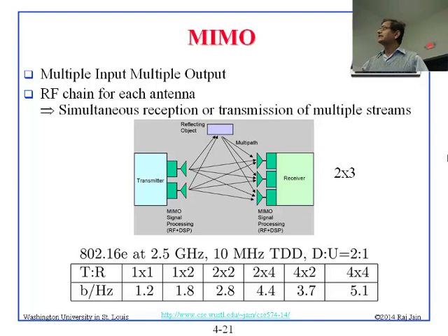That takes us to the next concept, which is MIMO, which you have heard before, I'm sure. But MIMO stands for multiple input, multiple output. Basically, if you go to buy anything today, it generally has more than one antenna like this. Right? In the old days, just 4 years ago, it used to be just one antenna, or maybe two, but basically only one would be used. So now most of the things have multiple antennas. Right? And not only at the receiving or the transmitting end, but both ends. So we have multiple inputs and multiple outputs. That is called MIMO.